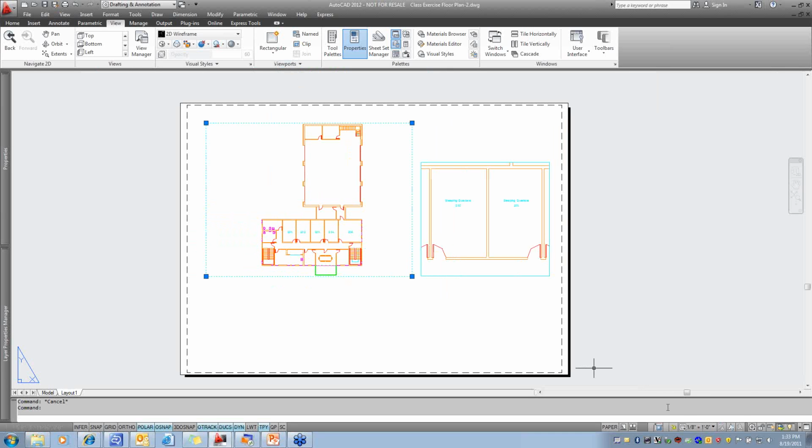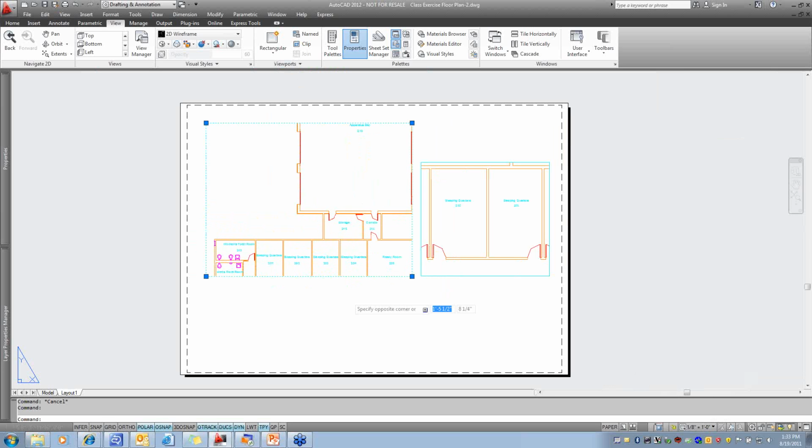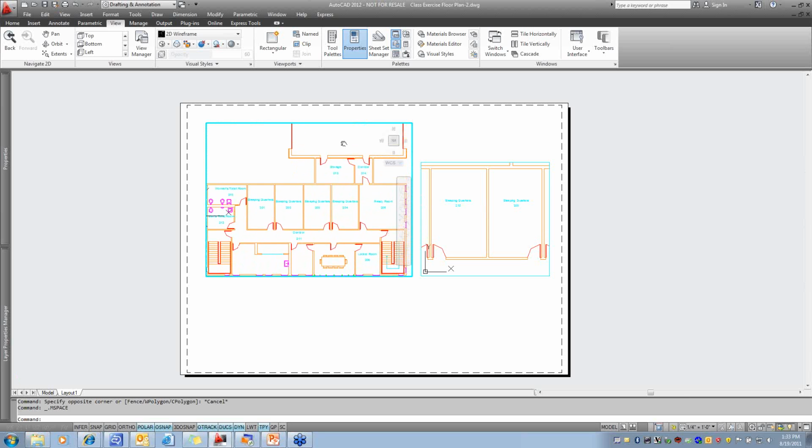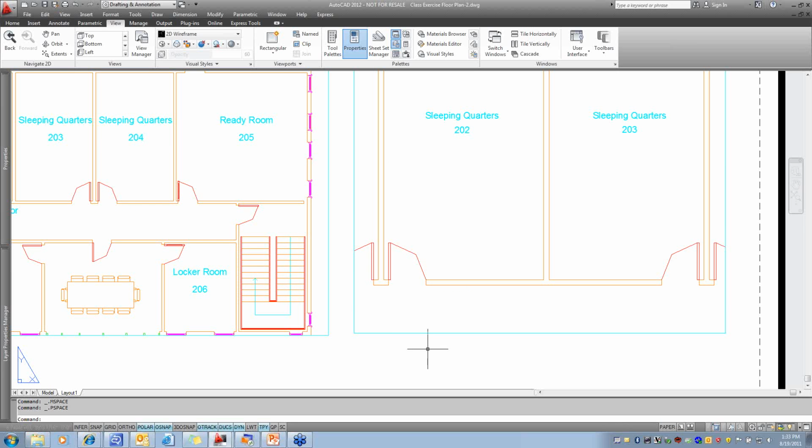If I'm going to do this, I'm going to change this viewport scale to 1/4 inch. You'll get a better illustration of it. Because now we're looking at the same items. So this is looking at my status bar, this is a 1/2 inch scale viewport. This is a 1/4 inch scale viewport, yet the text and everything looks exactly the same size because of what we did with giving the text the annotative property and assigning it to the appropriate scales. And that's what we're after.